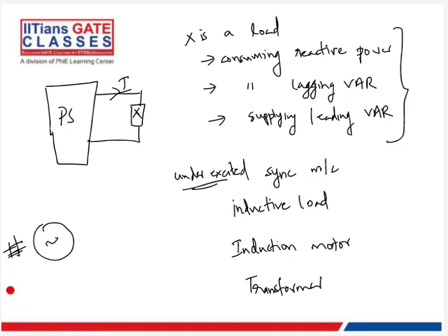But if the exciter circuit is not at the proper setting, then it needs more power to set up that magnetic field, so we will draw that power. Given an underexcited situation, the synchronous machine also needs additional power to set up the magnetic field. So it acts as a consumer of lagging VAR, right?